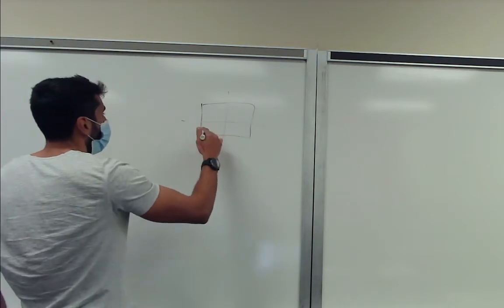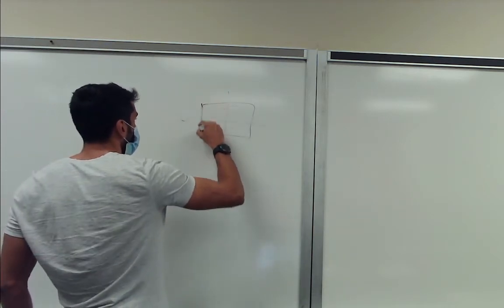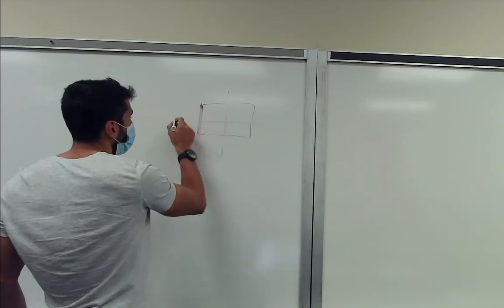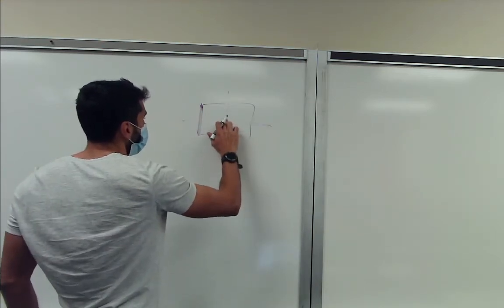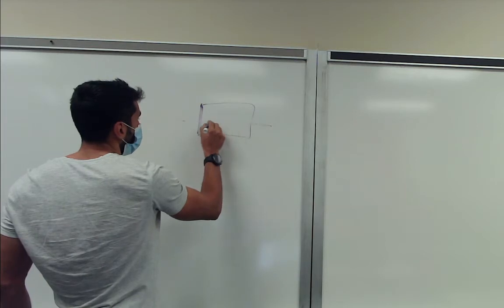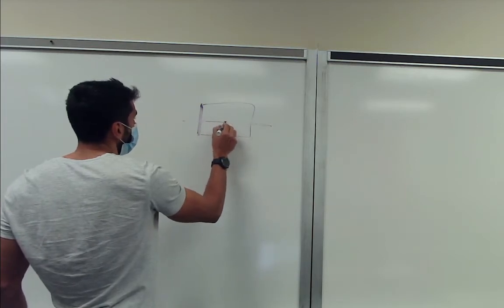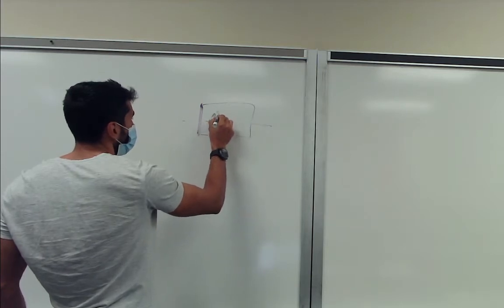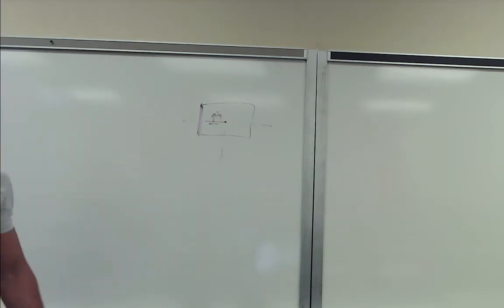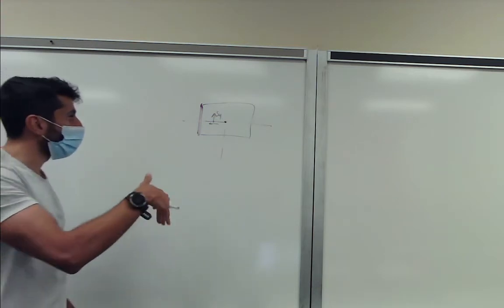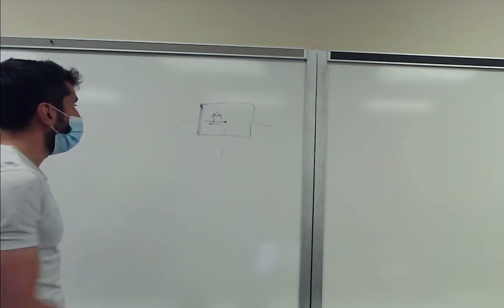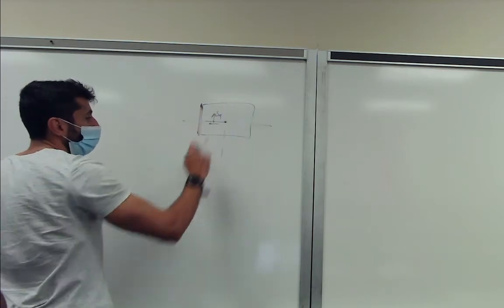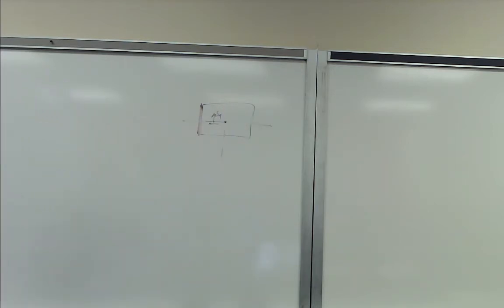But say, for example, you have a wing box and this side is thicker, then it will still lie on this axis of symmetry, but now you still have to determine which location, say from the midpoint center of the wing box, the shear force must act to create only bending. So just keep that in mind. And if it's a closed section, it will always lie within that closed section. There are a couple of tricks you can use to identify where the shear center lies and give it as a first check on your solution.